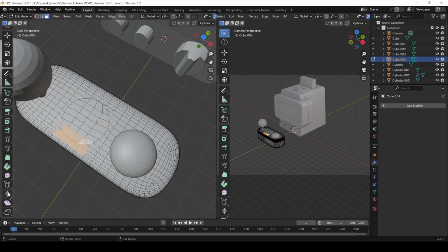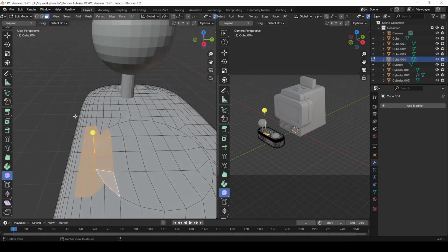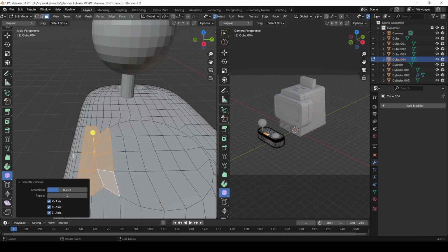Okay, and you go to here, go with this or middle mouse button and just go to shrink, edge slide, this one, shrink, and no, this one, smooth. You go to this smooth. What this does basically is it will smooth between the edges and make some space for you. Like, it will modify the geometry in a way that gives you some space. Like, let's do it like that. Now let's smooth it out or back. See, and just smooth it until it's almost intersecting, and just leave it like that.